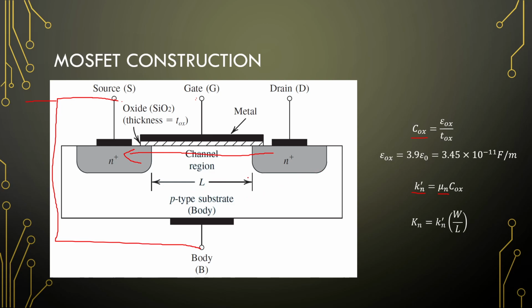So that is our MOSFET's transconductance, and this is for processes scalable with the width and the length of the transistor. So you can make your transconductance larger or smaller by scaling the widths and lengths of a transistor. So this is kind of similar to the beta value of a BJT, where that was the current gain. This is kind of a transconductance gain of the MOSFET.